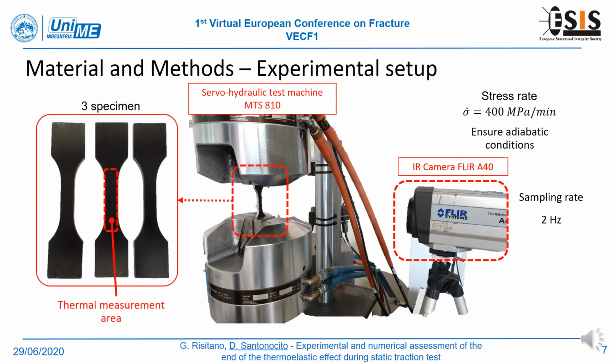The tests were performed on 3 specimens. Their surfaces were coated with high emissivity black paint on one side, and the maximum temperature value of a rectangular measurement area was recorded.